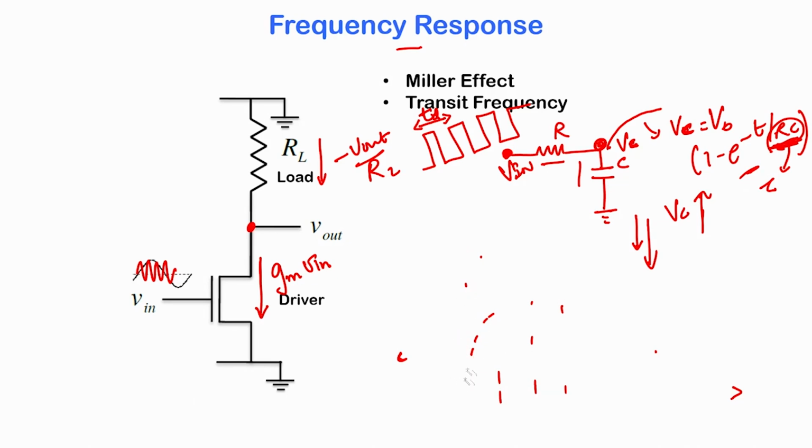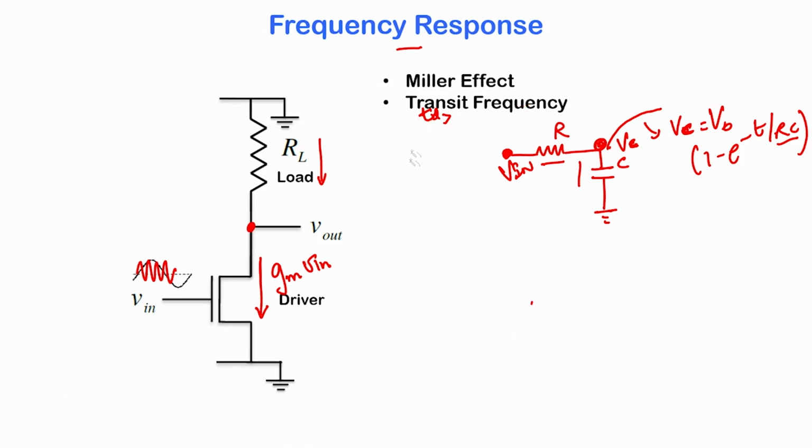So now let us come back to this amplifier here. So you can actually break down any circuit into R's and C's, series combinations of R's and C's, and by just calculating the time constants we will know whether the circuit can respond quickly or not. Now our interest here in this study on Miller effect has got to do with the input sensor. So let us say there is an input sensor which is sending in all your Vn signals, and those signals are all coming here, but the sensor has got some output resistance, which is normally the case. It could also be a previous amplifier.